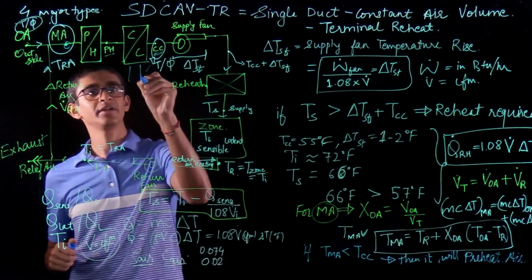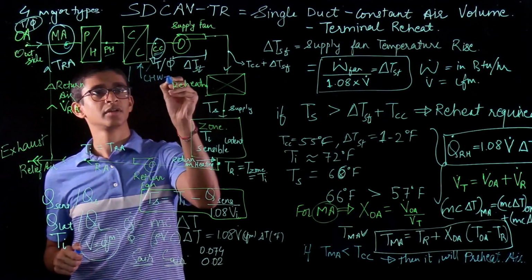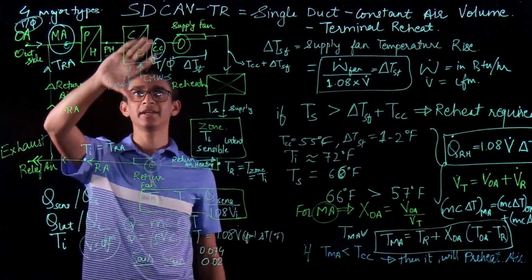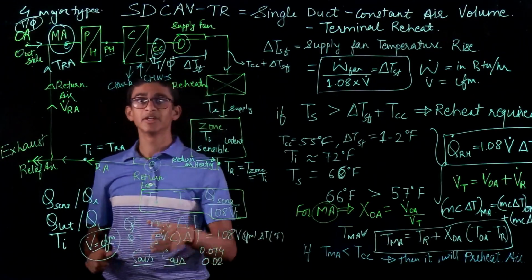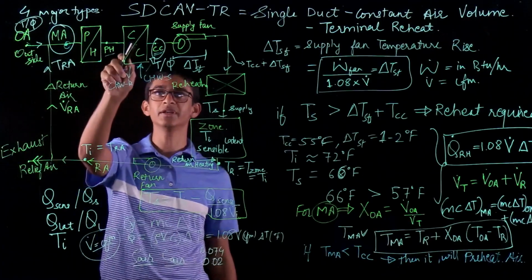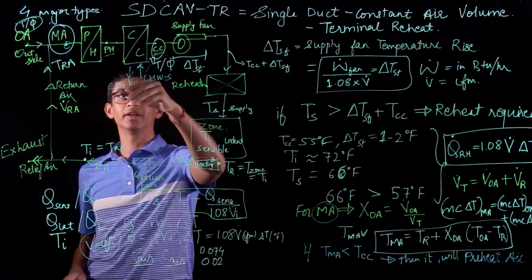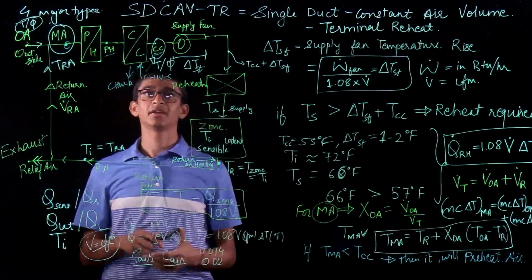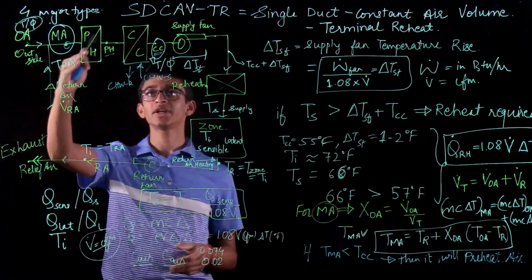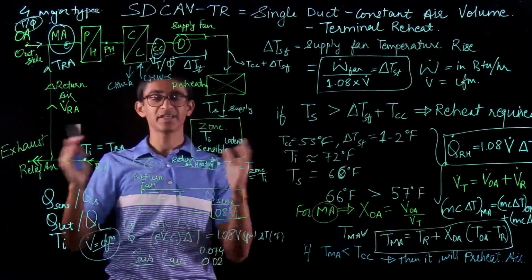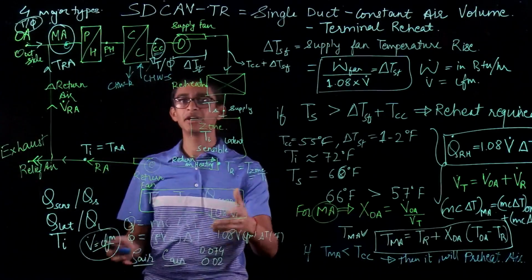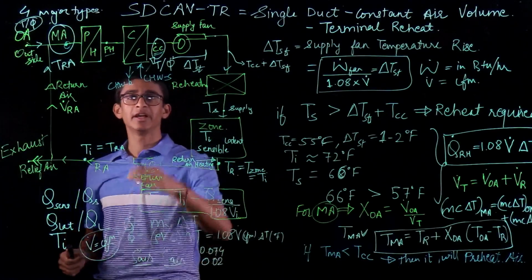In the cooling coil, we'll have cool water coming. So chilled water will be supplied, and the chilled water will be returned back. And when the chilled water supply and return happens, it is a kind of heat exchanger. The cooling coil is a kind of heat exchanger. So when the chilled water is coming, it transfers heat with respect to the air which is flowing over here, and the supply water is coming over there. So the supply chilled water, maybe it is at a temperature of 45 degree Fahrenheit and the air is coming at some 65 degree Fahrenheit or 70 degree Fahrenheit, then the air will get cooled to 55 degree Fahrenheit. That is set for the cooling coils to operate with, and the return water will maybe heat up from 45 degree Fahrenheit to 50 degree Fahrenheit, and that's how all the circulation happens.